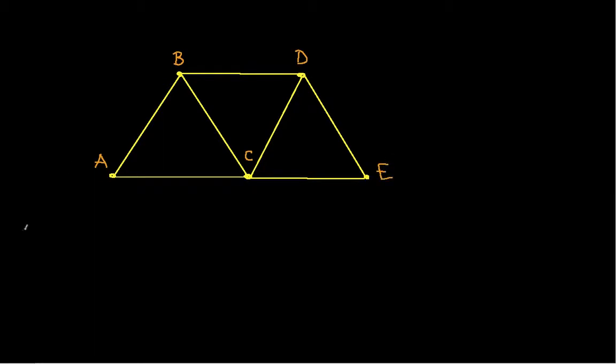And then we have the following reaction forces. On the left we have a pin joint, so basically our entire truss is free to rotate. This will give us an FAX. Oh, whoops. This will give us an FAY.